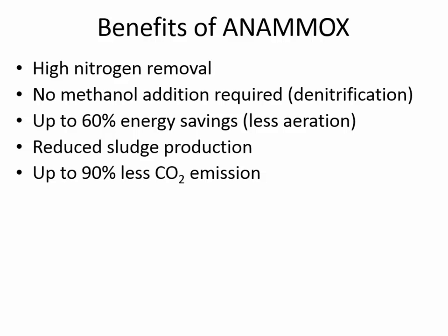The first is that there's a really high rate of nitrogen removal. It's very efficient and effective, and you can have a very pure effluent quality. You don't have to add methanol as a carbon source during denitrification, which you often have to do in traditional denitrification. Because you're aerating less, you save up to 60% of the energy that would ordinarily be required to remove nitrogen.